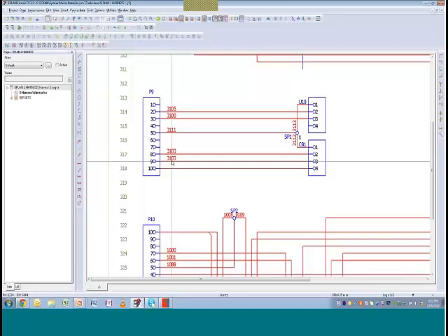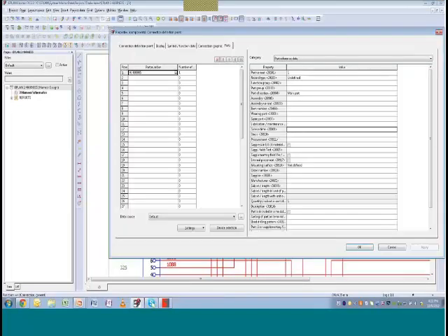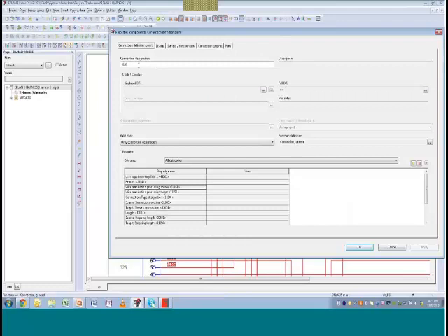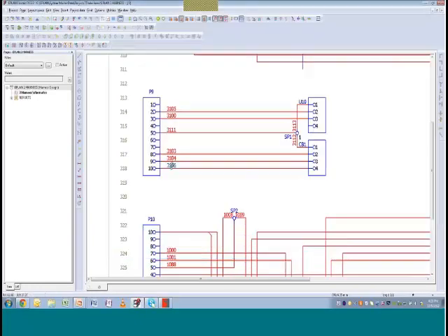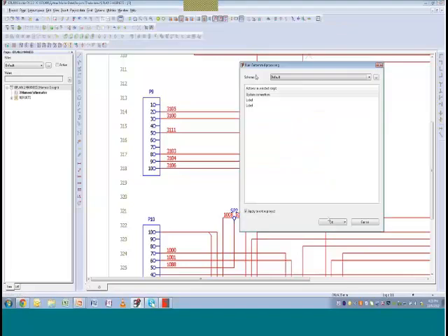here I'm just going to add a couple of wire tags. We'll change the wire number from 3103 to 3104, and then we'll do the same with this one and make it 3106. So now we have 2 new wires that are going to pins 9 and 10 on the P9 connector, and then on the CB1 we've added the 3 and 4. So now I'm going to go ahead and export my information again, my wire list.